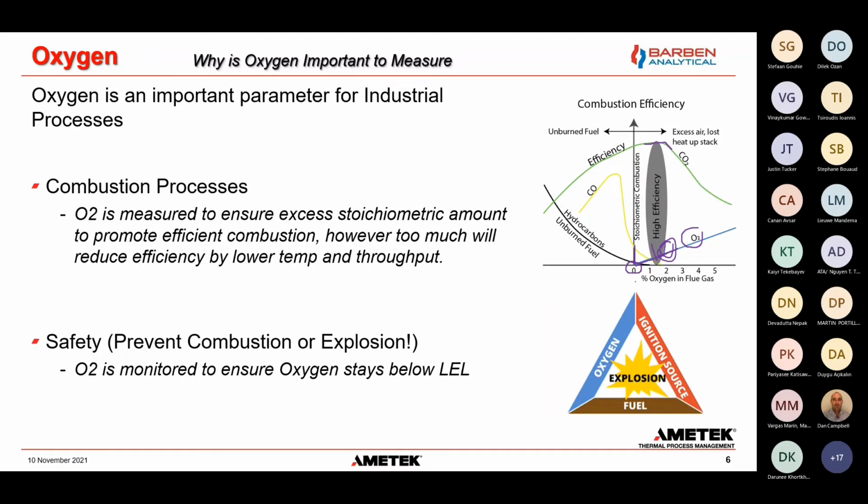And then the second most common reason would be safety. In this case, we want to prevent combustion itself, in the form of an explosion. O2 is monitored to ensure oxygen stays below the lower explosive limits.